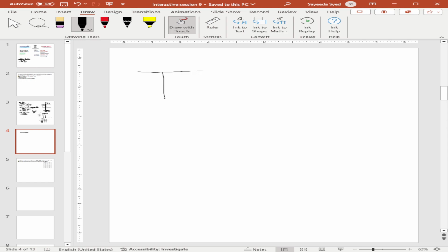If the material has good frictional resistance along the shaft of the pile, there will be a frictional resistance along the shaft. That is the first mode of transmission, and that is what actually happens when you load. First, the load is dissipated through this friction.